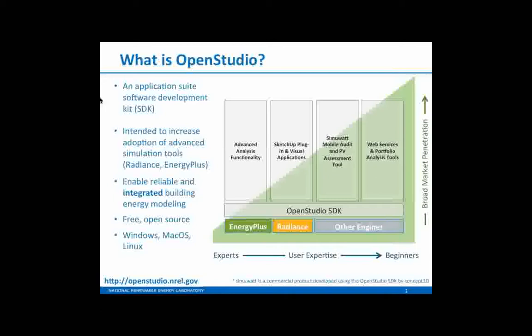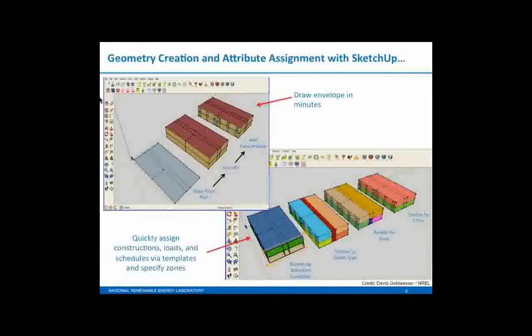And so really quickly, they're just some screenshots of the idea behind building a simple model using, in this case, SketchUp. There's an OpenStudio plugin which allows you to make a 3D form in SketchUp and then apply metadata to that building form that energy modeling tools and daylight simulation tools understand, like wall reflectance and constructions and HVAC equipment and all those things, and export that to OpenStudio and do your analysis. You can also import IFC or GBXML, so you're not limited to just using SketchUp.